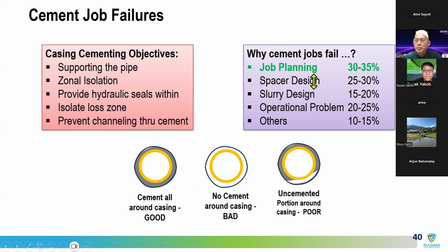Special design should be able to clean up all the mud cakes and so on, before you have your cement touching the formation. So actually, it's like a cleaning process before we put cement. So special design, if it's not proper, if it's not large enough in terms of volume, you have failure as well. So this is the statistic of failure of jet cement, recorded worldwide by the cementing company.